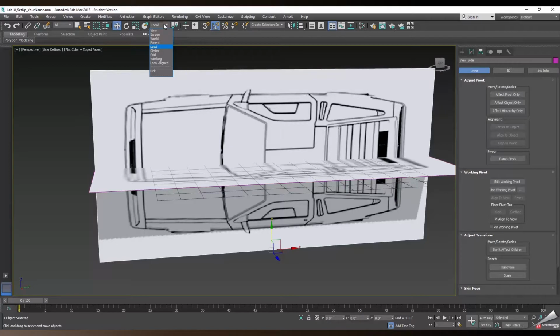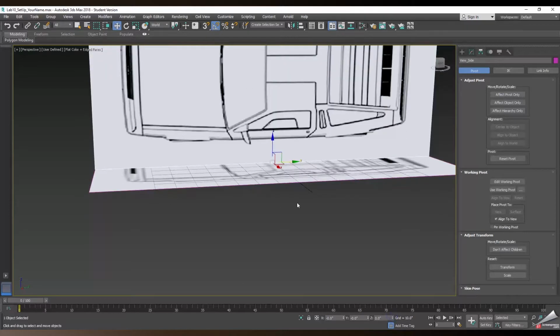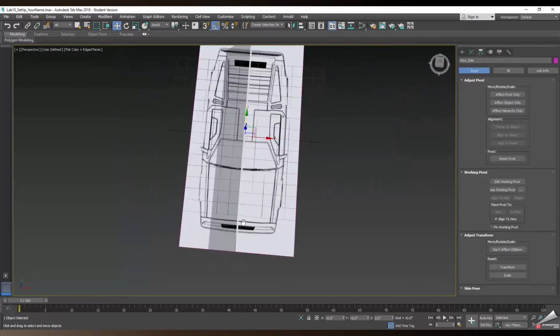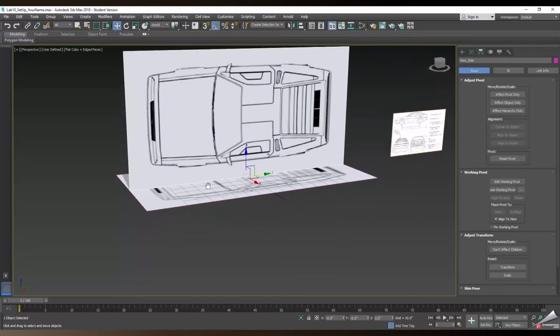Change your coordinate system to world and watch what happens. Here on the z-axis, everything's 0. It was zeroed out before, remember? This changed to negative 50 because I lowered the anchor point negative 50. So just zero it out. There we are. Perfect. Right on that ground. Lovely.